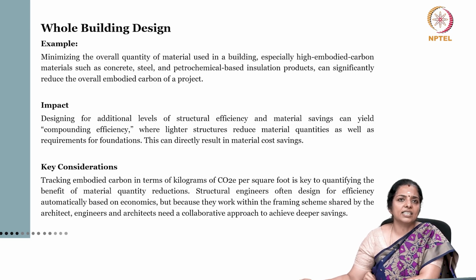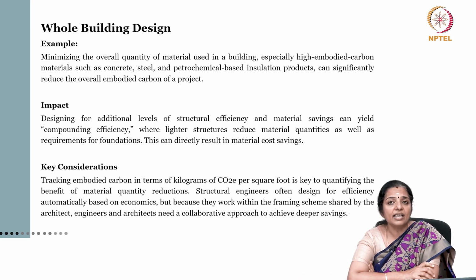So, the key consideration is that tracking embodied carbon in terms of kilograms of carbon dioxide equivalent per square foot is key to quantifying the benefit of material quantity reductions. Structural engineers often design for efficiency automatically based on economics, but because they work within the framing scheme shared by the architects, architects also need a collaborative approach to achieve deeper savings.